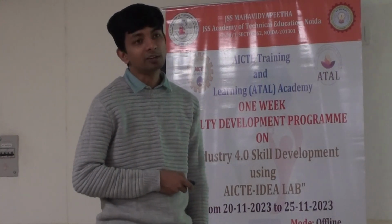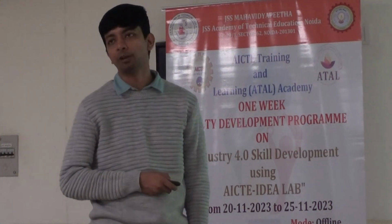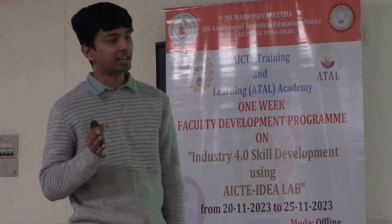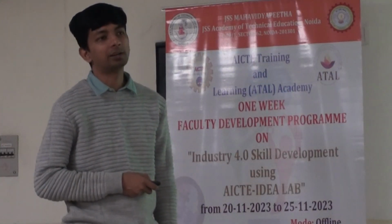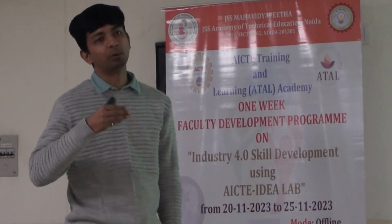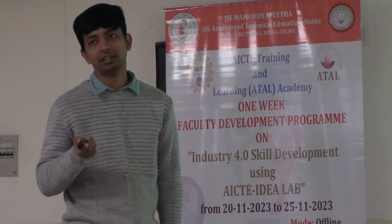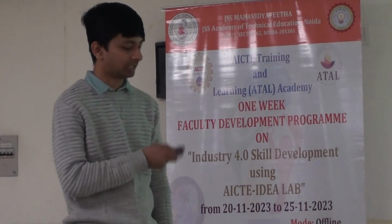This is again important to know because you should understand the requirement. For example, if you have a requirement of say 200 micron kerf to be always maintained for your application, which can be very precise, then obviously you cannot afford to have a 300 micron spot diameter itself, because then once it cuts, it will always be more than 300, right? So you should understand the requirement, and accordingly you can select the particular lens and particular laser source which can give you a spot diameter less than the kerf. So that is the selection criteria.